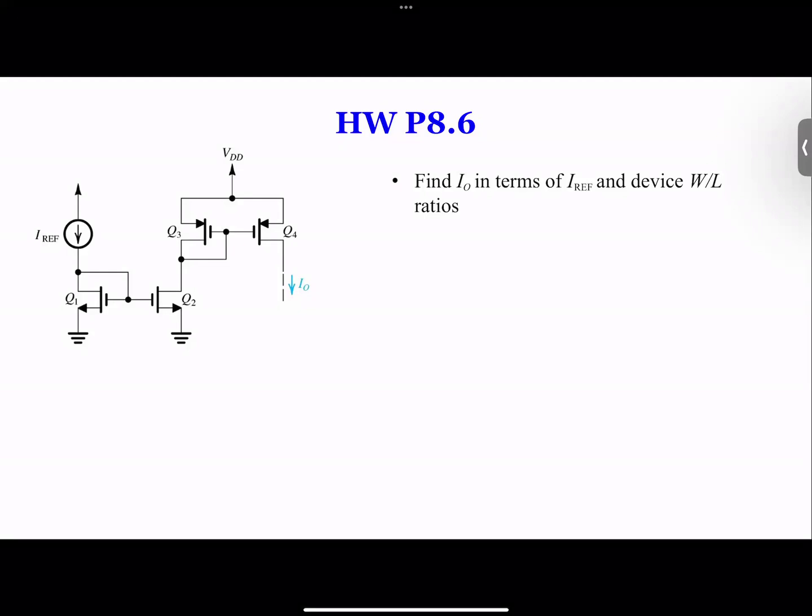And then they can have such a small voltage drop across the drain and source, like the overdrive voltage of only 0.2, VT is 0.2 to 0.5, but BJT has 0.7. So you need much less voltage to drive, and current-wise, much smaller. So nowadays, in highly integrated circuits, very large integrated circuits, BJT is used less and less. Mostly I use CMOS or MOSFETs. CMOS, later on we'll talk a little bit. It's just a PMOS and an NMOS together to form a CMOS, complementary MOS, it's called.